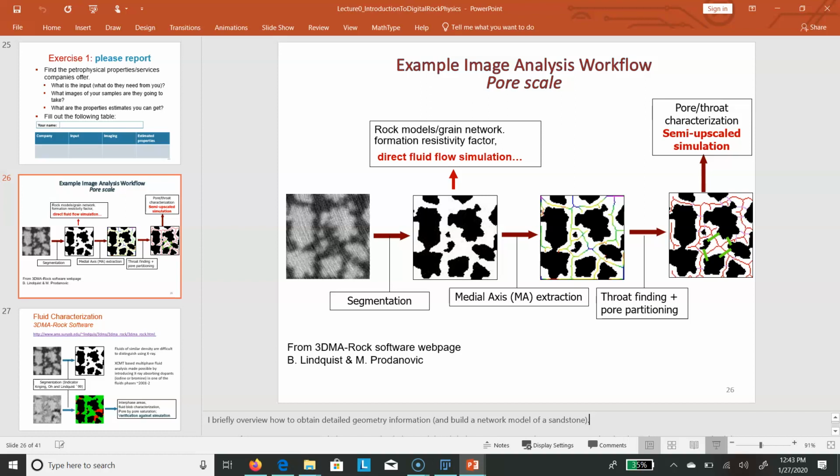For single phase permeability, all is well. Most of the flow really goes through that middle. And whatever inertial stuff you have happening near the boundaries, it's so slow that it doesn't matter. Where it starts mattering is for two-phase flow, where it's that inertial stuff and stuff on the side that ends up trapping fluid.